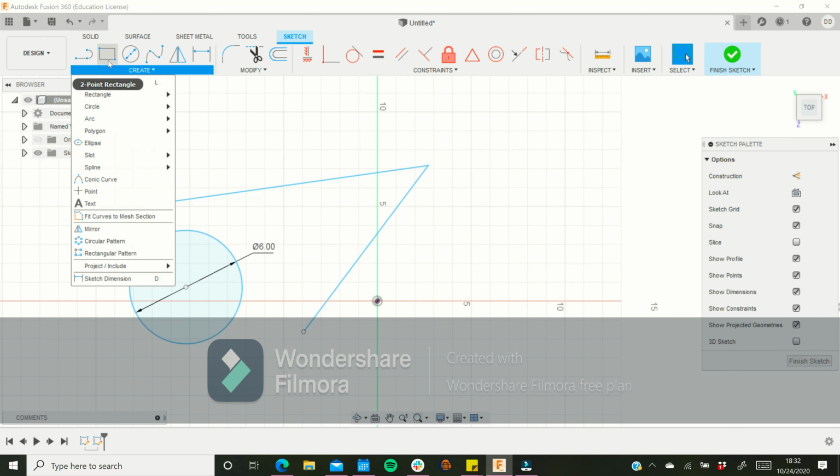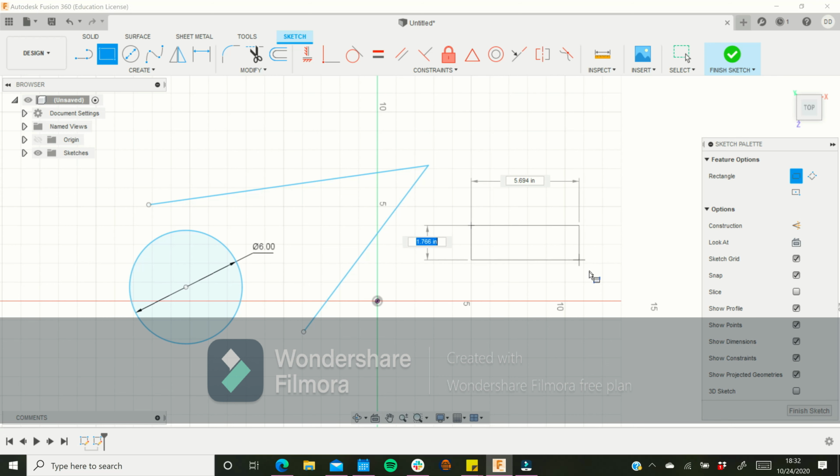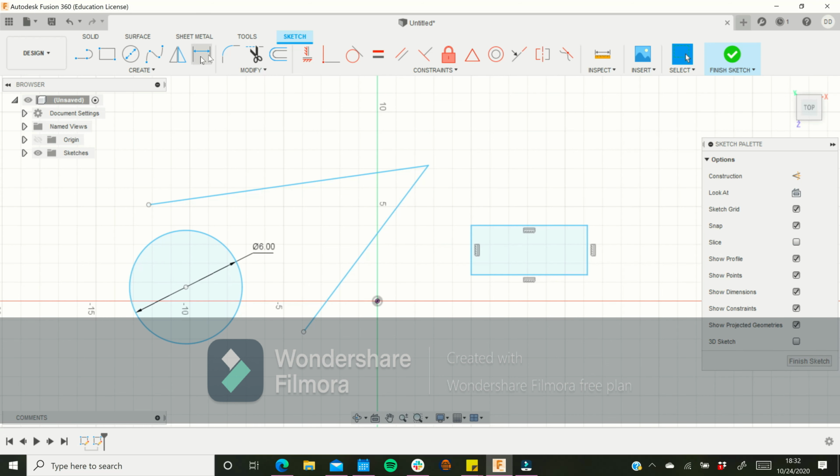And finally, how you dimension a rectangle. Say I have this rectangle right here. You can dimension it like this, and then you dimension the next side, and then you have a nice dimensioned rectangle. If you wanted to make them the same length, you could edit this one, and then you could just click on this one, and it would just set it to be the same thing as that first dimension, no matter what. So now it's a square, and this goes for everything.